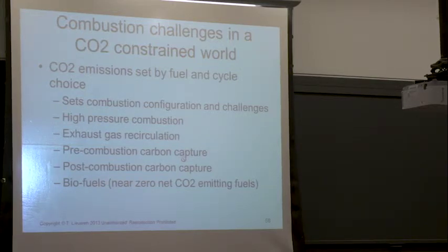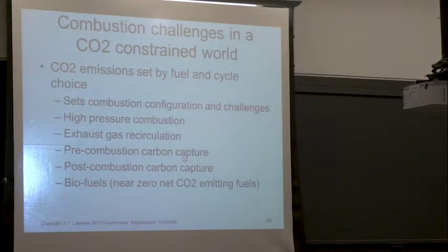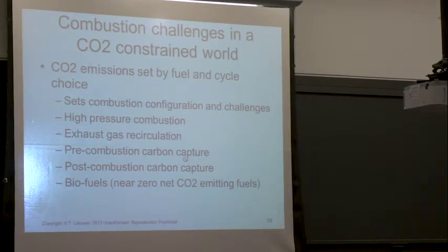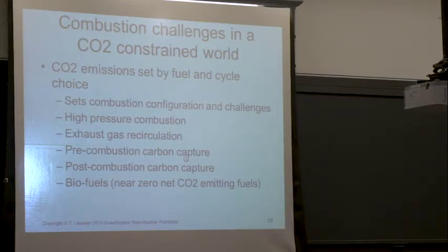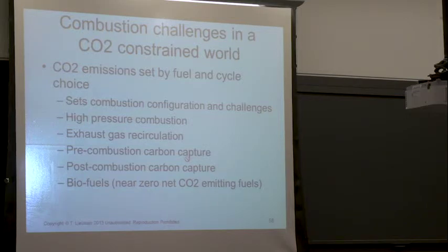It's an interesting question, but in fact, there are a lot of really interesting combustion challenges in a low CO2 world, even in a zero CO2 world. All right, and so we can talk about those. So as we said, CO2 emissions are going to be set either by your fuel or by your cycle choice. So for example, a cycle choice, if you're burning a hydrocarbon, you're going to make CO2, nothing you can do about it. The job of the combustor is to make CO2, right?